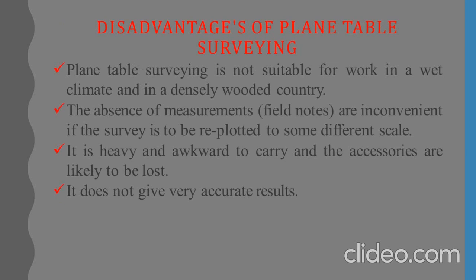Here I will also add some of the disadvantages, because all things have some pros and cons. So here are some of the disadvantages of the plane table survey. Plane table survey is not suitable for work in a wet climate or in densely wooded country. The absence of measurements, that means field notes, is inconvenient if the survey is to be replotted to some different scale, and it does not give very accurate results.